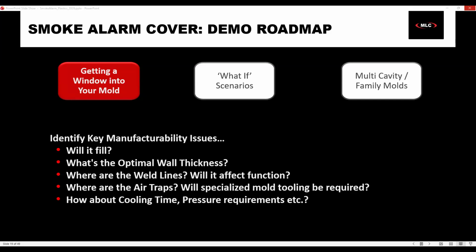An air trap occurs when you have air inside of the cavity and then you're pushing material into that. The air is getting moved and pushed into a single place. So if there's not any type of ventilation that is considered, you could end up with these air pockets that occur either in the plastic or they could actually end up almost bursting, and then you get a physical defect on that. So that can be an area of concern. There's quite a few here. That's because there's text. So that would make sense.